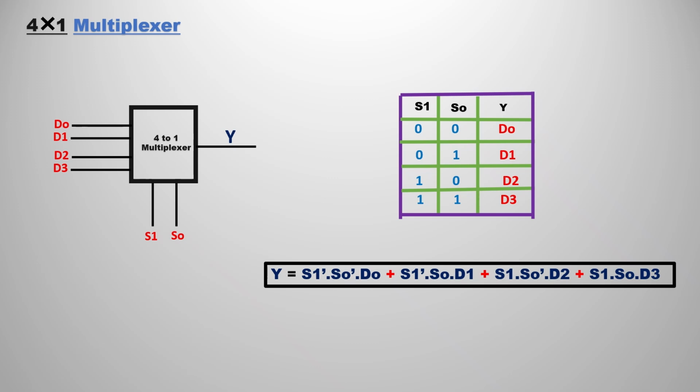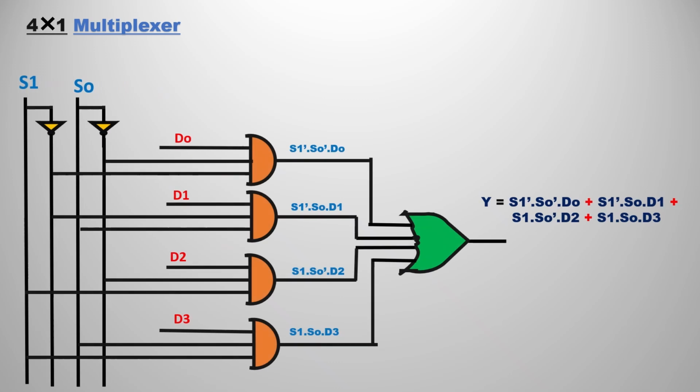Like that you can fill in all of them, as with the 2x1 multiplexer, and this is known as the SOP format. So you can write all the SOP terms and add all of them. This is the final output expression for Y for the 4x1 multiplexer. If variables are changing, write according to those variables. You can clearly observe the Y output expression over there.